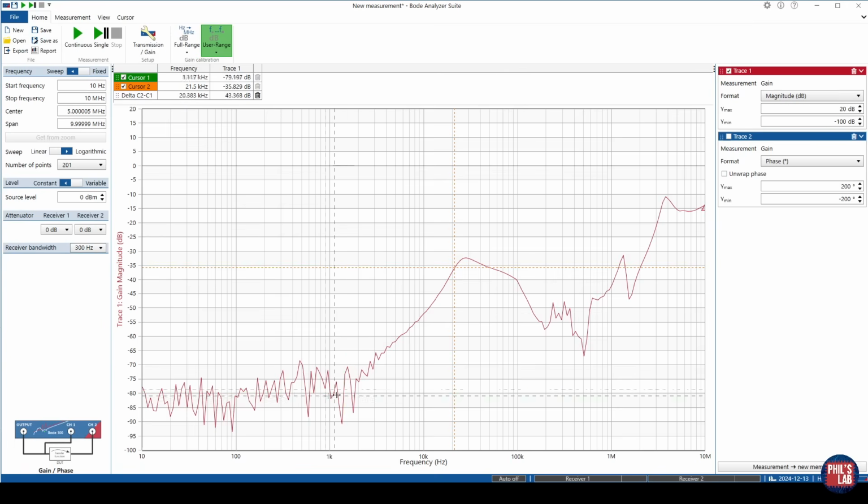So in the frequency range where the control loop is dominant and strong and quick, the negative feedback is great because it increases the power supply rejection ratio. Input signal disturbances are attenuated quite significantly.